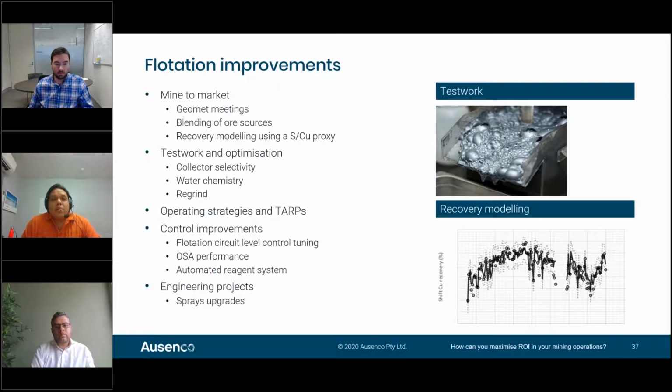With a quite similar approach, we also improved the flotation circuit. As I mentioned before, we have ores coming from 3 mines, quite different from one another. And the flotation circuit is challenging to control without understanding the metallurgical domains. The key driver for performance is pyrite, which is abundant in certain domains and at times difficult to depress to achieve the target concentrate grade.